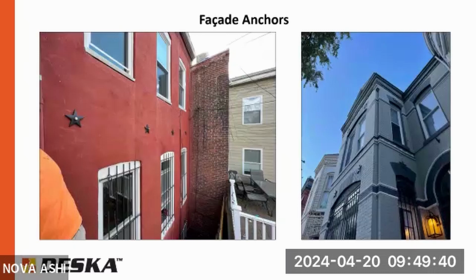And so then the wall bulges outward, and then it creates a lateral deflection issue, kind of the opposite of the foundation issue where it's being pushed inward. In this case, it's pushing the exterior wall outward. And we call these facade anchors or wall anchors, just depends on the construction. But these get tied into the floor structure, and they prevent it from bowing outward anymore. But again, if the root cause of the issue is the lintels, they must be addressed as well.